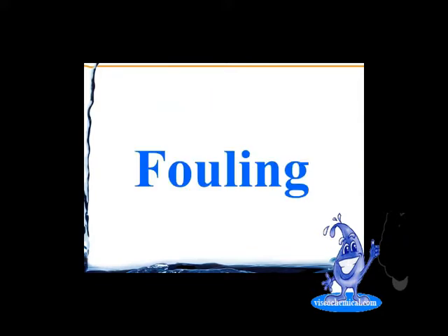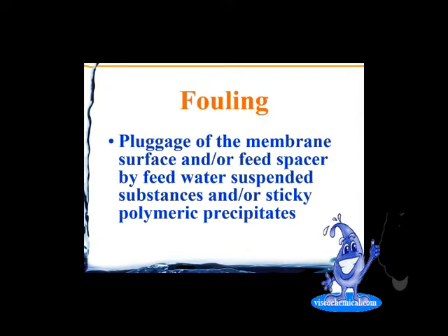Okay, so that's just a quick overview of scaling. Now let's take a look at fouling. So here again is our definition, not a universal standardized definition. For fouling, we're talking about particles, living or non-living particles. Living particles are mainly bacteria. Non-living particles can be anything from silt, sand, clay, precipitates like iron, rust, things like that.